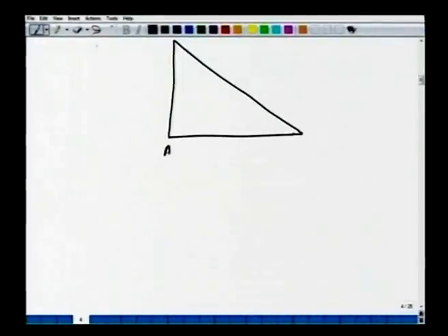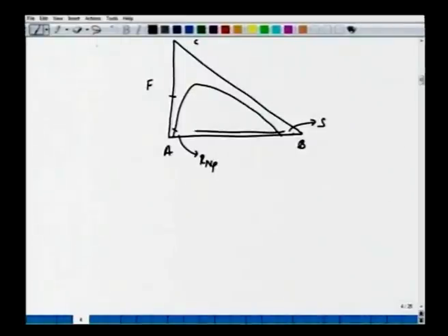So we have A, we have B, we have C, this extract, this equilibrium curve here. We said the point F is fixed, we have S fixed here, we have R and P fixed here. And this is a line which extends in this direction. If we keep on increasing the amount of solvent, then E1 extract will move in this direction. So S goes in this direction, E will go in this direction, and the line connecting this E to F, which gives us del R, moves in this direction.